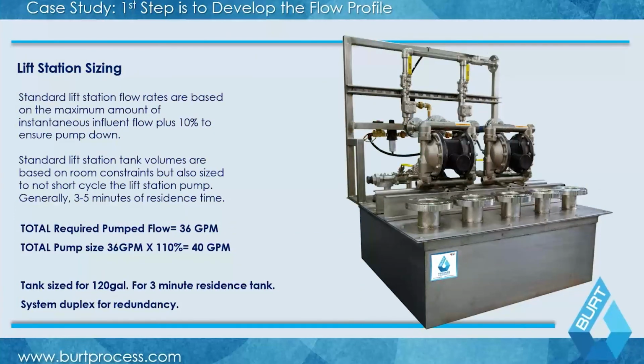So lift station sizing is a little bit different. Those tend to run a residency time of about 3 minutes, and you always have to pump them down. So you're generally applying a 10% oversizing to your lift station. So you're looking at about 40 gallons per minute of actual calculable flow from your lift station.